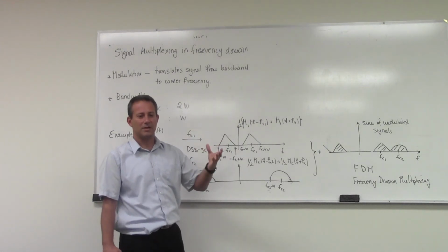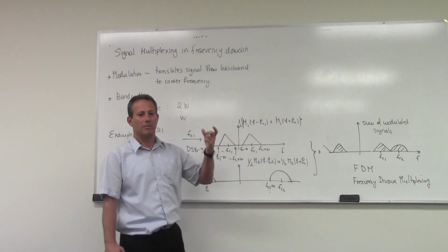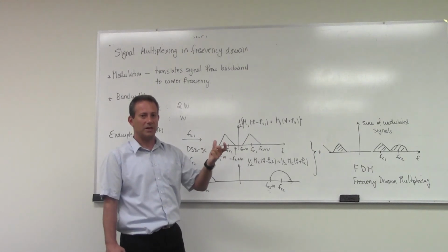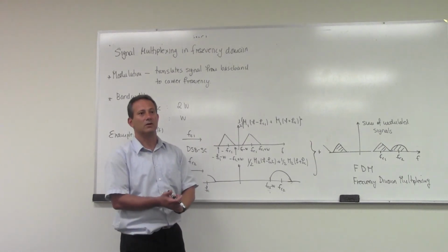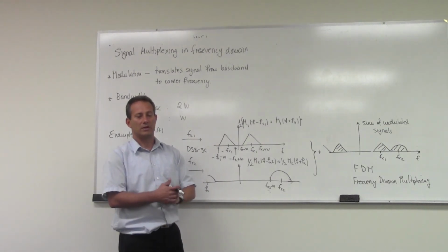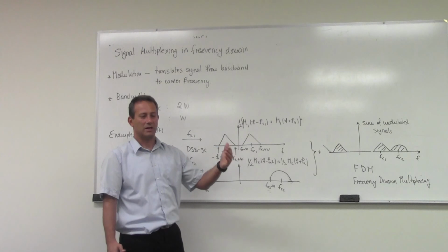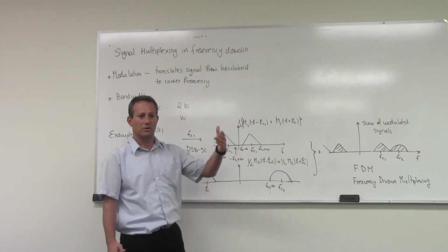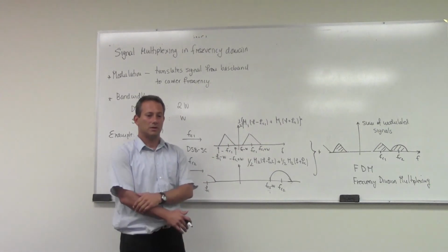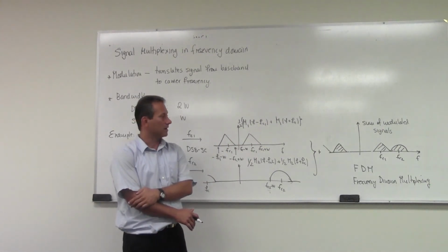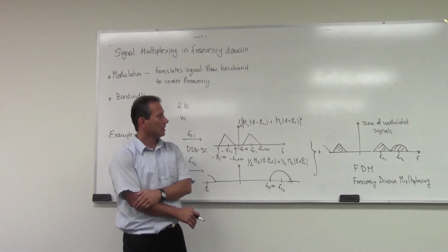It's using double sideband with a large carrier, but the bandwidth at the baseband is 5 kilohertz, and then it's translated to a few hundred kilohertz. The AM broadcast is, I don't know exactly, but 5, 6 to 11, 1200 kilohertz. So sub 1 megahertz of the carrier frequency.